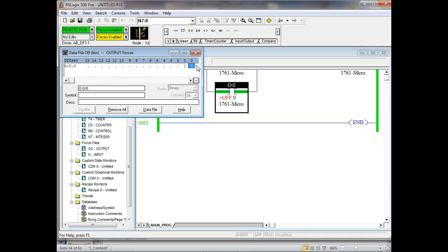It'd be screaming. And we was in there playing around, and I was forcing an output, and those side clamps were coming down. But the problem is that luckily they was running a narrow strip, and the clamps missed. But if I'd have stopped that thing when it was running 700 feet a minute, it would have crammed that thing up. So be careful and understand when you force these things.